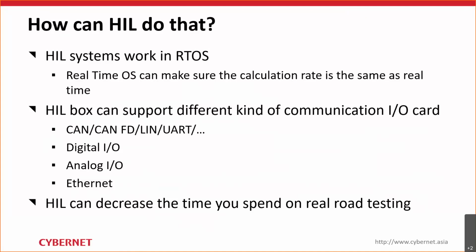You might have lots of communication channels like CAN, LIN, digital input-output, and analog input-output. HIL box can help you to use this I/O without any delay. You can also set some simulated fault signals to test your controller. Last but not least, HIL box can decrease the time you spend on real-world testing.